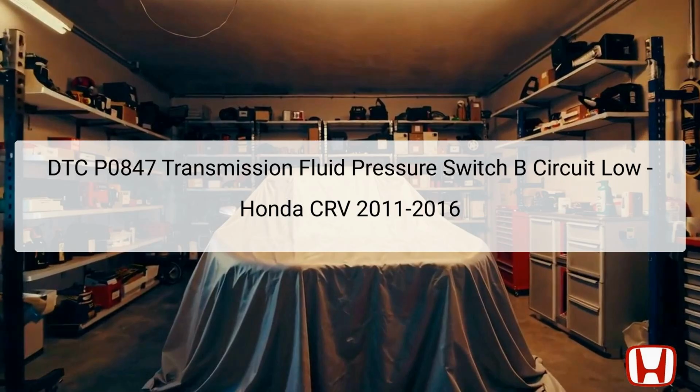In this case, the key components involved include the transmission fluid pressure switch B and the powertrain control module, PCM. The transmission fluid pressure switch is typically located on the transmission itself, and its sensors send signals to the PCM to inform it of current pressure levels. The presence of this DTC may lead to a variety of transmission problems, underlining the importance of diagnosing and addressing